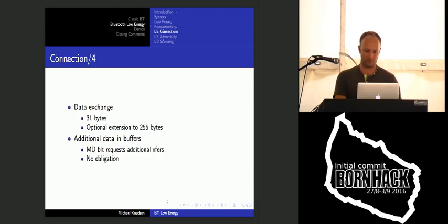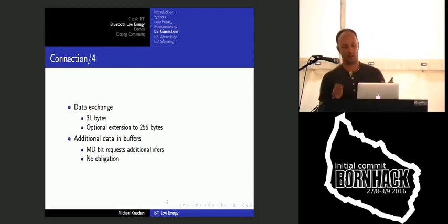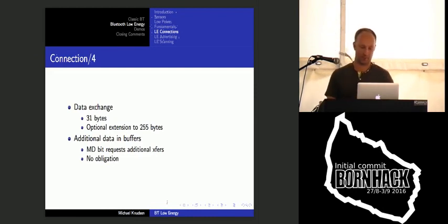So even though we can set a fairly high connection interval, so that we sleep for a long time, we still get to transfer a lot of data, albeit somewhat slowly, when we get to the connection point. So this is reasonably flexible.